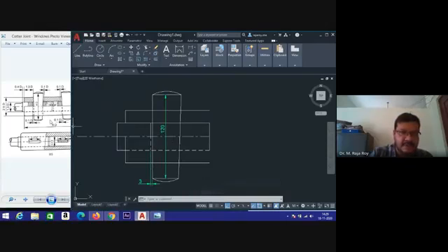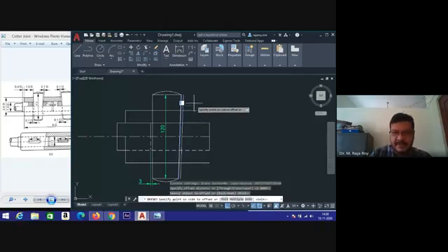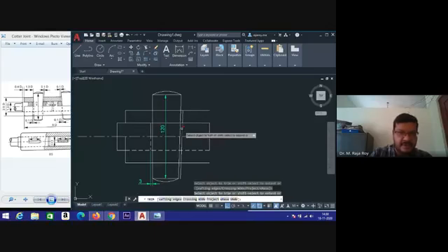Now this portion here and here I have to apply hatching. Here also I have to maintain some offset. For this also I have to maintain offset 0.1, that means 3 mm. Go to the offset command again. Offset distance is 3. Select this length. Go to 2. And this portion I don't want, this portion I want. Here I don't want, here I want. Something like this.